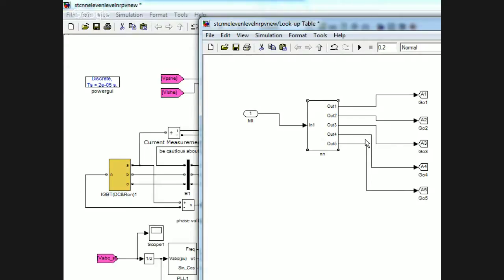Driver ICs are required, and another thing which is required is optocoupling, because the controller is digital and your circuit is analog. Not only that, the power level is different. This is only 24 volts and that is 440 volts. If you directly connect the higher potential to the lower potential, your current will flow and your controller may burn out. So in such places you require optocouplers or transformers. Isolation transformers are also there. You can have isolation transformers or you can use optocouplers.